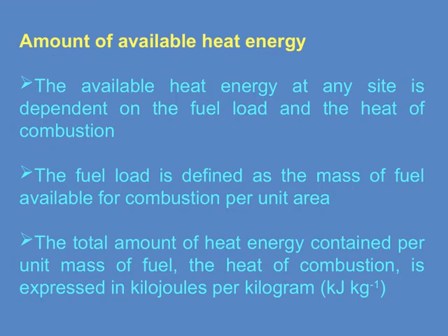Now, let's talk about the amount of available heat energy at a given site. This essentially depends on two key factors: the fuel load and the heat of combustion. The fuel load is defined as the amount of fuel available for burning per unit area. That is, how much fuel is physically present in a specific space. The more fuel there is, the greater the potential heat energy that can be released.